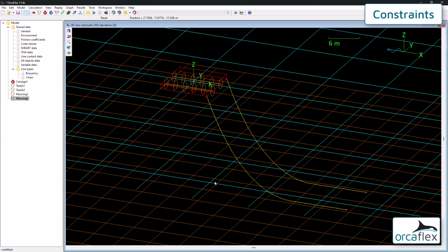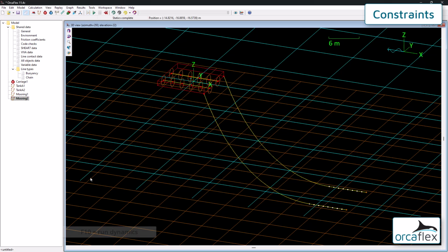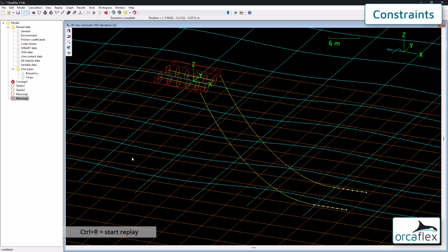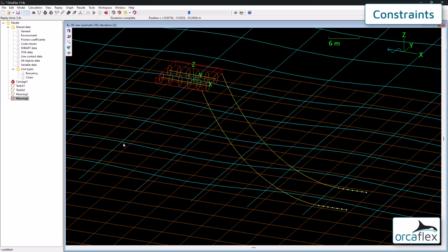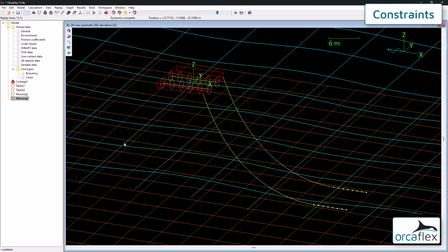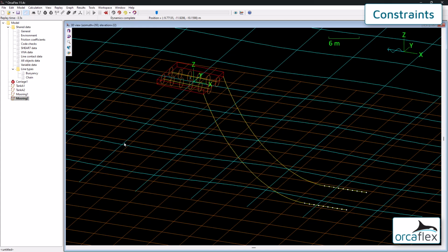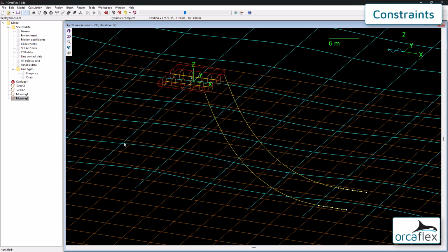Even though we only have one of the 3 rafts, we should now be able to run statics. We can even run dynamics and look at the response of a single floating raft. However, power generation from a wave energy converter like this comes from the relative rotation between rafts, so we need at least one more.